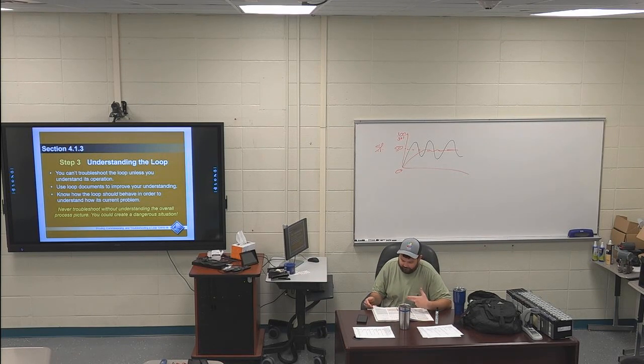Going into 414, troubleshooting the loop. First paragraph on page 22, I've got the third sentence highlighted. In testing the loop, you could begin at the power supply and verify that you have 24 volts DC.